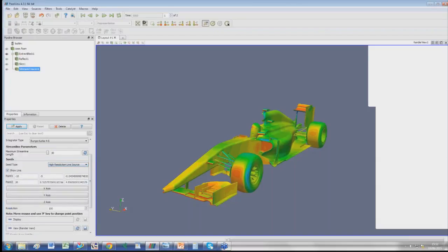And then you need to enter the X, Y, Z of 2 points that define the line. In our case, we wanted -1, 0, and then 0.1, so it's slightly above the ground level. And then again, -1, -1 in Y, and 0.1. And just click Apply. That's done it. Okay?